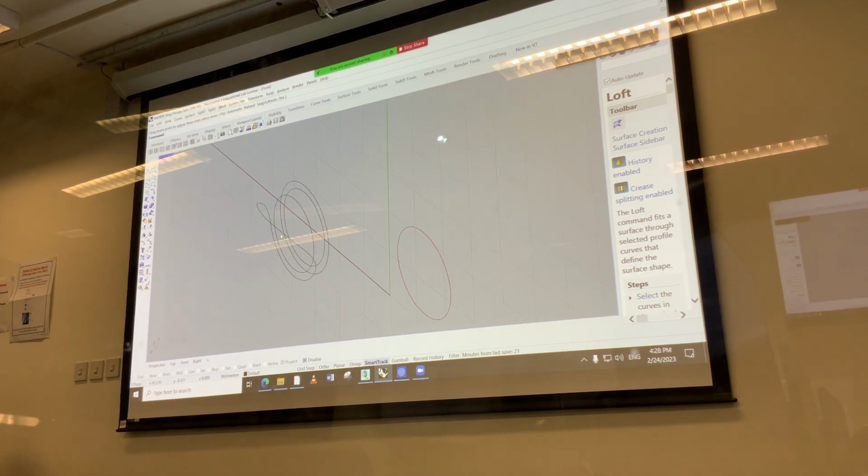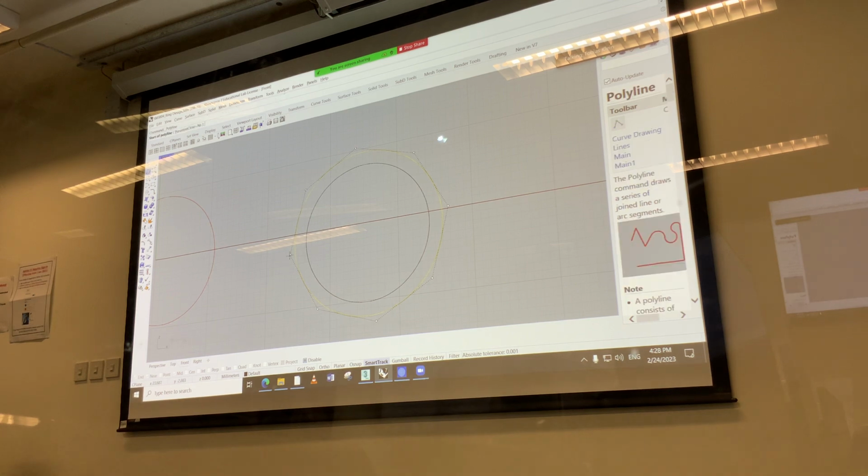Okay, one of the things that I looked at though is that this element here is not symmetrical. You see that? When we go to front view, this one is not in the middle. And that annoys me because it means that the whole ring here, if I would make a line from the control points, from point to point, this point here, it's actually not horizontal. So that really annoys me, because that means all my commands when I switch from left to front view or so are slightly wobbly. Unless you like asymmetry when you're building it, I would recommend not working with this.